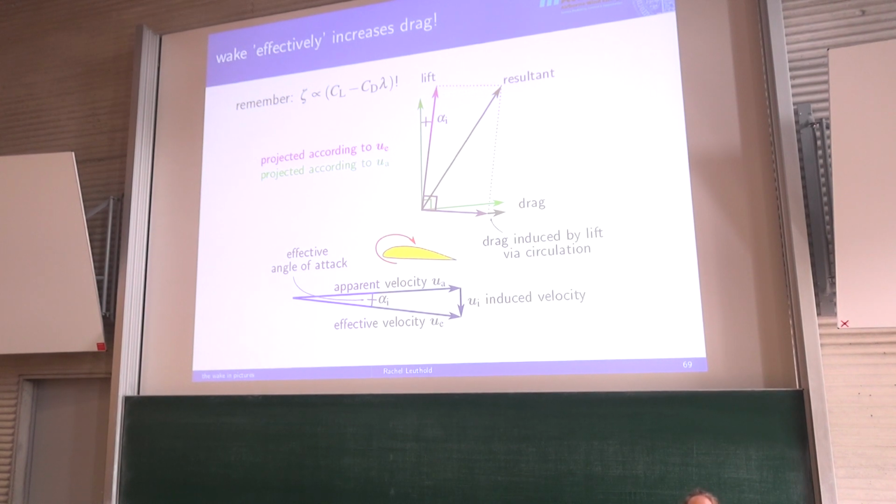Yes, Frank? Is this effective velocity just the velocity after it's past the wing? Yeah. So to be entirely fair, we should be doing this at the center of pressure of the airfoil. We should be doing this more or less a little bit behind where this circulating pattern is originating. But again, yes, it's always downwash that we are using to calculate this, so it's always downwards.